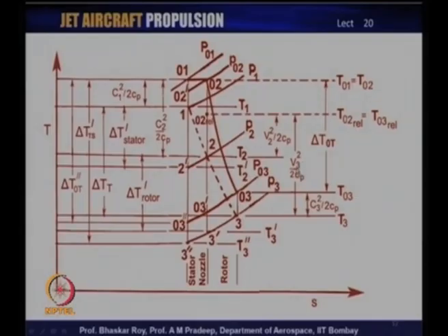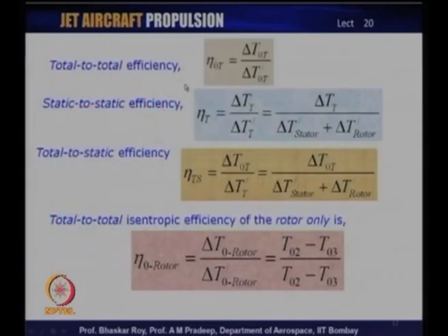So, this is how a typical gas turbine indeed works. We can quickly now say that the total efficiencies of these turbines can be cast in the form of efficiency parameters in terms of total efficiency drop through the turbine as opposed to the isentropic total efficiency drop through the turbine.